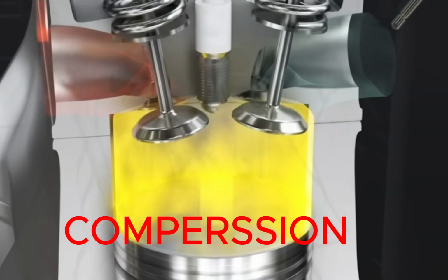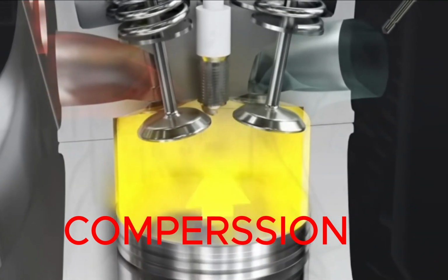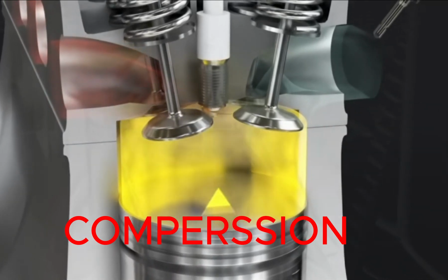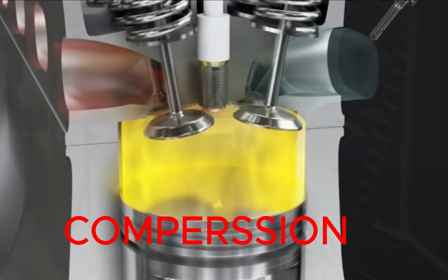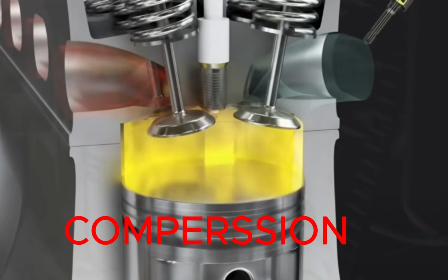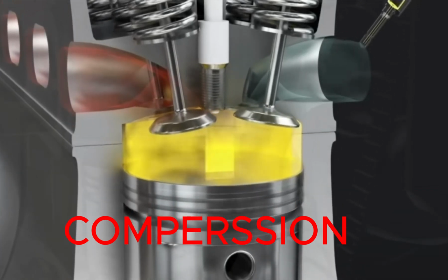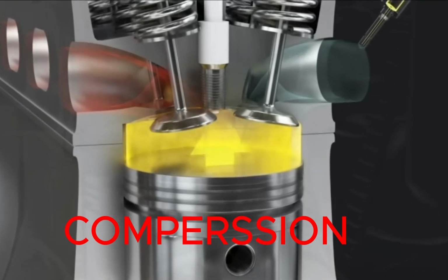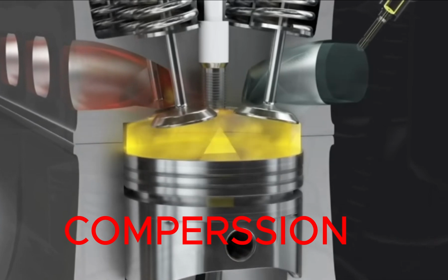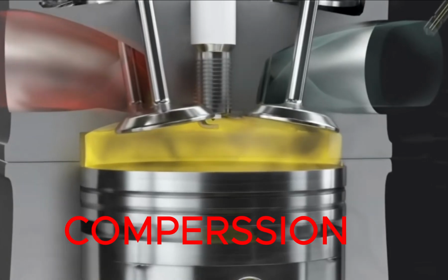2.2 Compression stroke. The piston moves upward, compressing the air-fuel mixture. Both intake and exhaust valves remain closed to increase pressure inside the combustion chamber. In gasoline engines, the mixture is compressed to about 10 to 12 bar, preparing for ignition. In diesel engines, air is compressed to an extremely high pressure, 20 to 30 bar, raising its temperature to around 500 to 700 degrees Celsius, hot enough to ignite the fuel when injected.